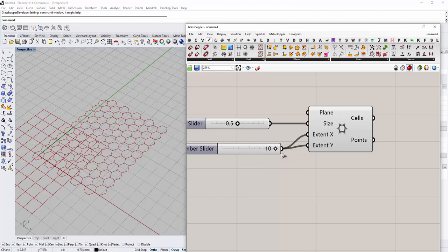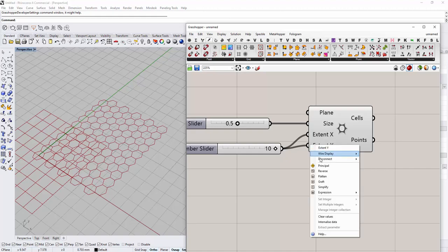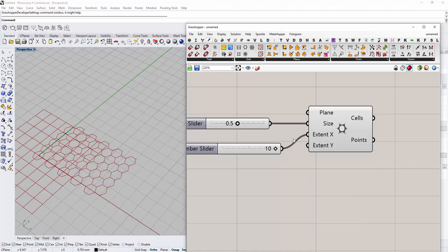It's also worth mentioning, if you want to disconnect one of these lines, you can hold the control key. It shows you red, and here you can disconnect these lines. There's also another way to disconnect: right click, go to disconnect, and disconnect this number. Anyway,